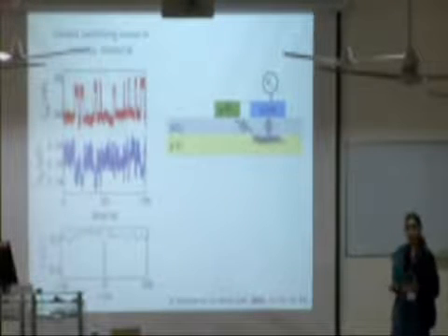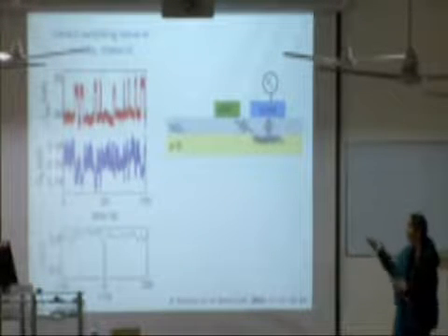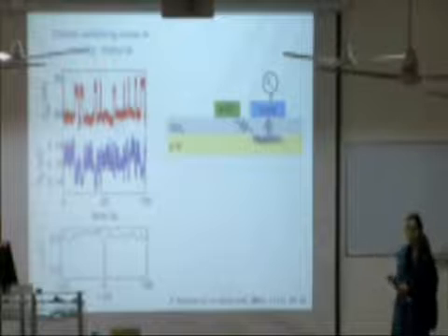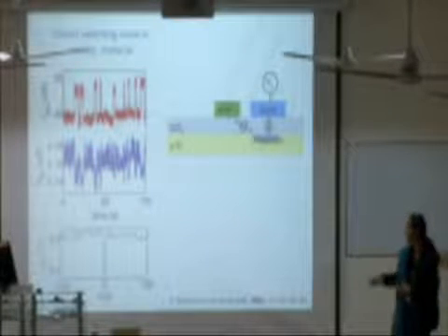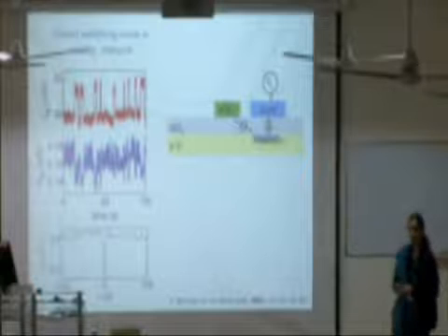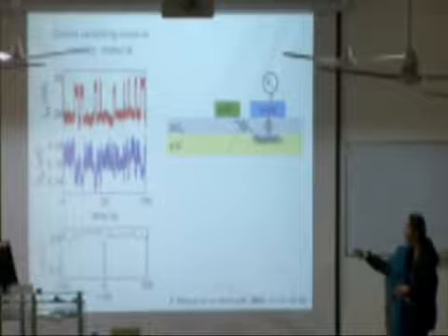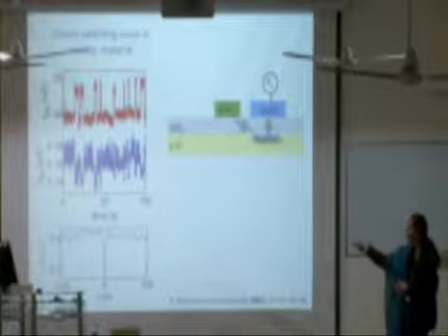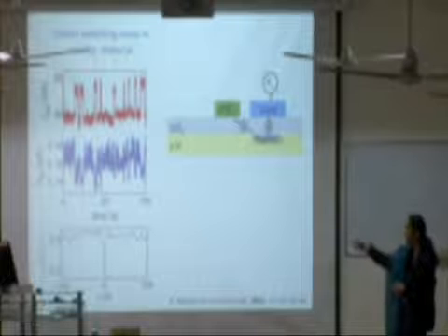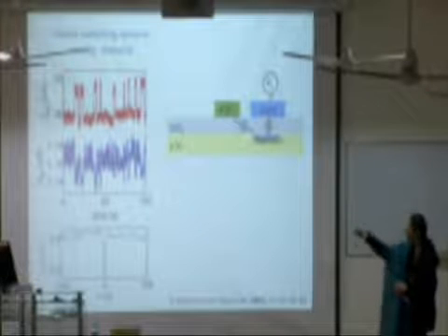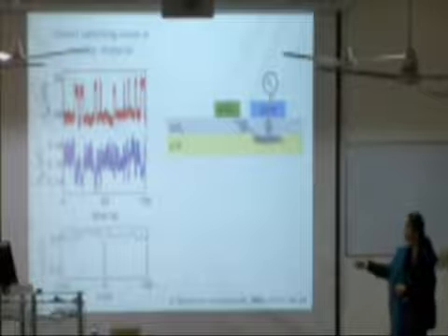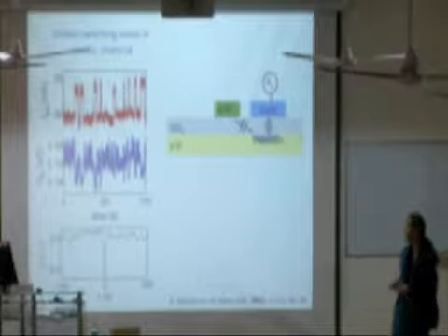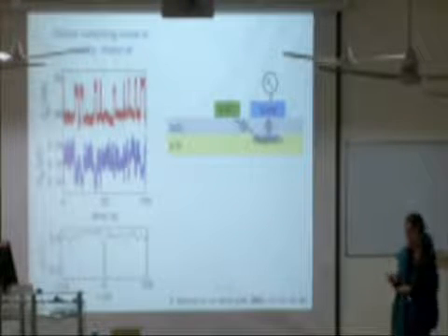While there are many advantages of our MOSFET, there are two more that I would like to highlight. So for some of the resistive materials that we were studying, we saw telegraph noise coming from the material. And our sensor that was patterned next to the material also detected this telegraph noise in the form of these switches. And by doing a correlation analysis, we showed that this switching was perfectly correlated, so our MOSFET can detect switching noise in a nearby material.